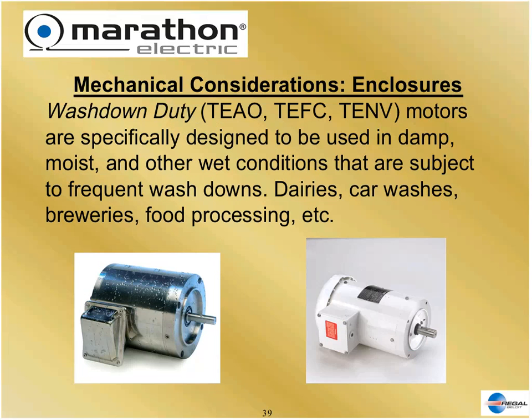Basically, we have two types at Marathon Electric. We have the WashX motor, which is a white one. It's painted white, and it is for not such demanding applications, but they are washed down. The white paint is not only a rust preventative paint, it is non-toxic, so it can be used in food processing in case any of the paint were to be flaked off the motor.